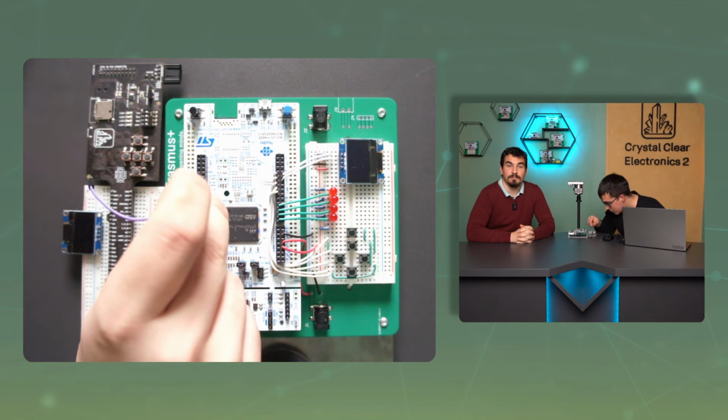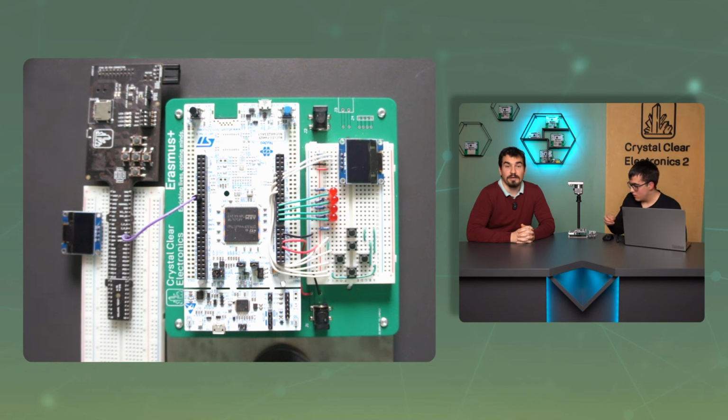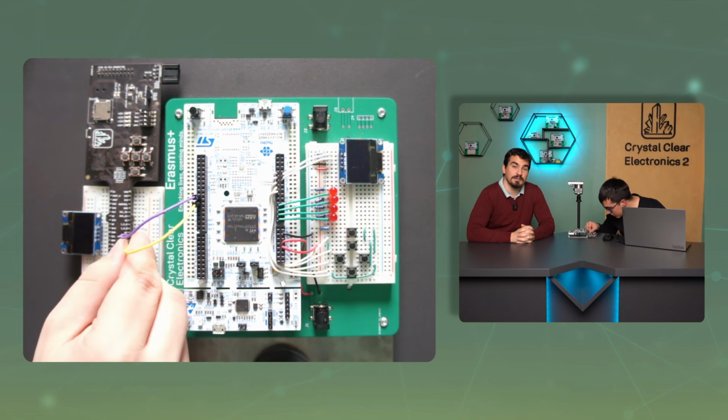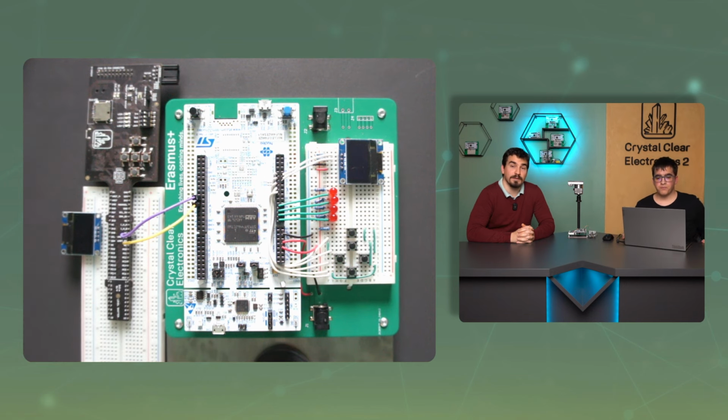We've looked at the UART settings, but before we get started, Balázs, please help me demonstrate how to connect the two devices. Alright. The two development boards can be connected via the UART TX and UART RX outputs. The TX leg of one panel is connected to the RX leg of the other, and vice versa. If you want to test the program with only one device, connect the TX and RX outputs on the breadboard through a 10 kilo ohm resistor so that you will receive the data transmitted from the TX leg of your module, essentially talking to yourself.